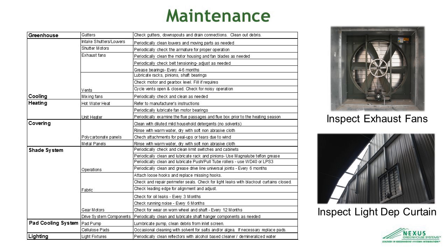Shade systems you always want to listen to just to make sure that you don't hear any loud buckling or any kind of indicators that you might need to grease your rack and pinion system. You're listening for maybe stress on the motors at that point of the drive. Exactly. Keep an eye on the drive system, see if it's having issues. Of course, all the motors come with set limits, so if they're being worked too hard, they would turn themselves off. So it's important to keep a watch on the shade cloth and the blackout curtain to make sure that it stays in alignment, but they tend to be pretty maintenance free.